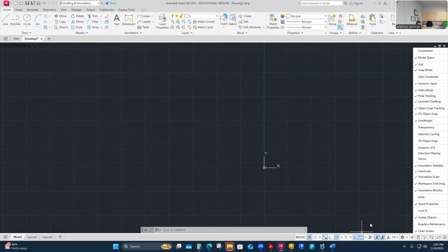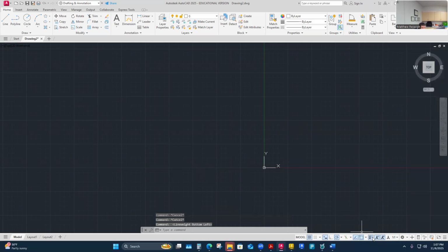One that I do make sure that I don't turn on is line weights. This is considered show and hide line weights. If it's loaded, it looks kind of like a paragraph sign or something. Thick and thin lines here. I make sure that one's turned off. Otherwise, you're going to draw with the line weights. And actually, when we draw, we like our line weights to be turned off, so all my lines will kind of look the same.